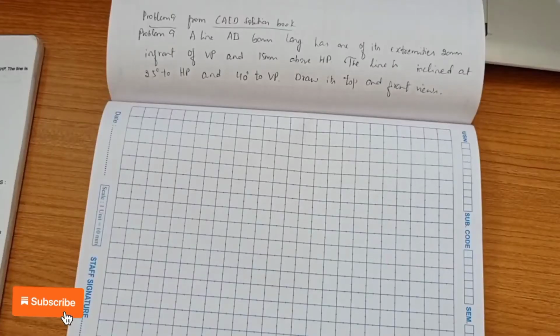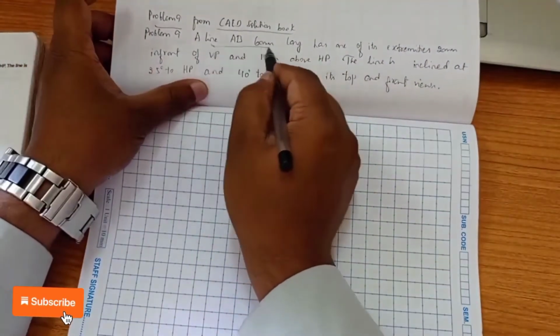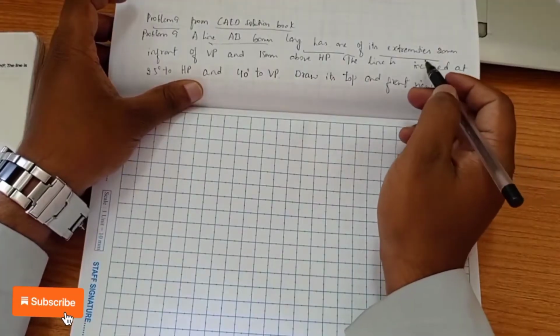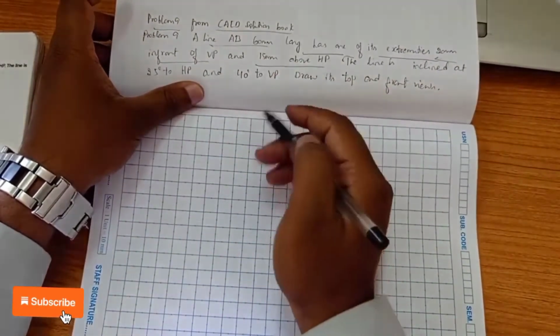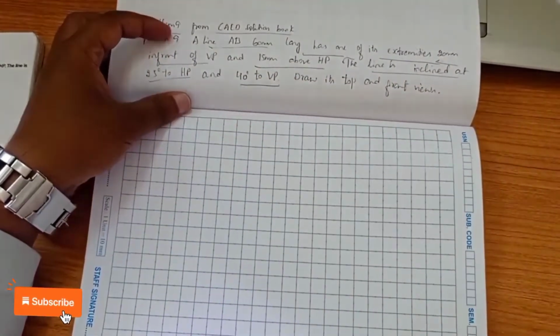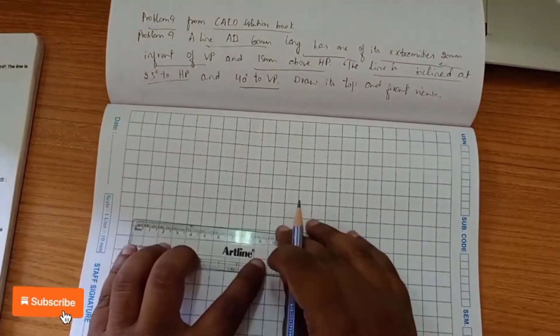Okay, we solved the problem number 9 from CAD solution book. You can see in this problem they have given line AB 60 mm as one of its extremities. Extremities means end point. Okay, so 20 mm in front of VP, 15 mm above HP. The line is inclined at 25 degree to HP and 40 degree to VP. So now we'll proceed with our solution here.